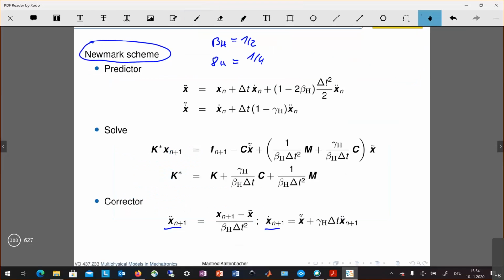Okay, so this was an overview about the mechanical field. We have seen all the different constitutive relations we have between mechanical stress and strain, and that for some cases we can reduce the full three-dimensional problem to a two-dimensional problem, in this sense that we have a plane strain or plane stress or an axisymmetric setup, and then result in a two-dimensional computation.